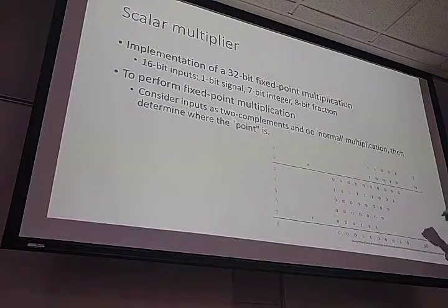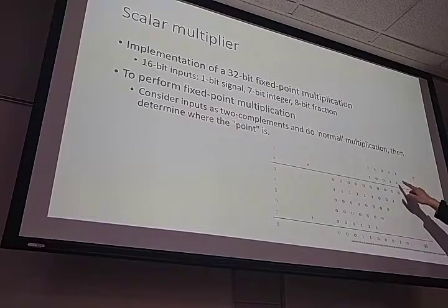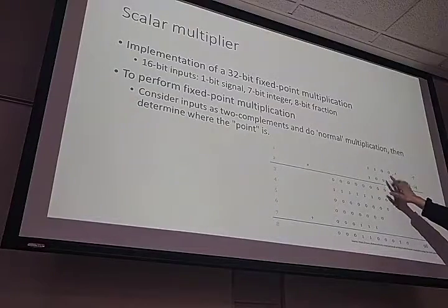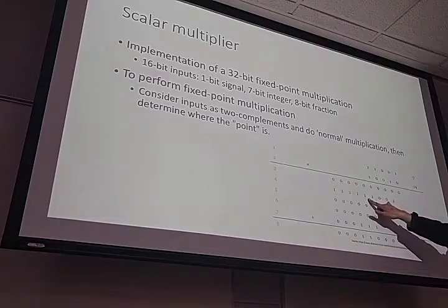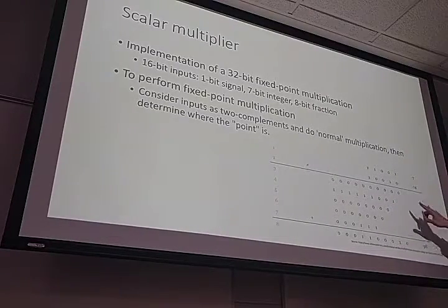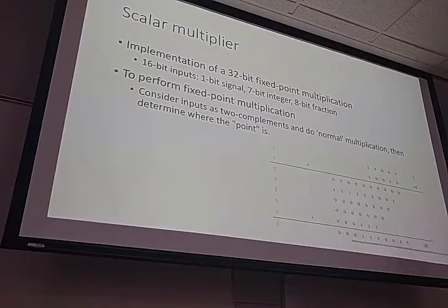Basically, when you have 0 in this bit, you just add zeros, and if there is a 1, you shift because of its weight and add it to form the next parcel, and if it's negative, you propagate the ones.